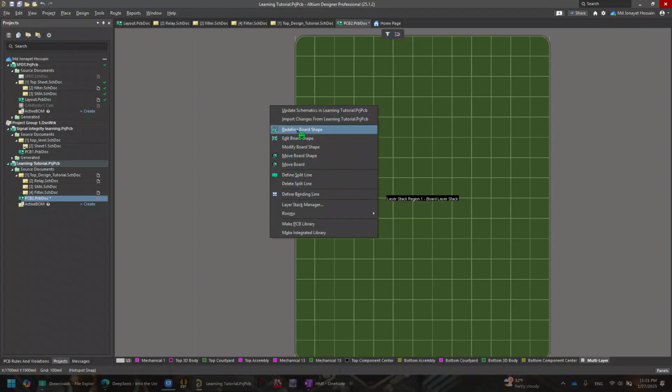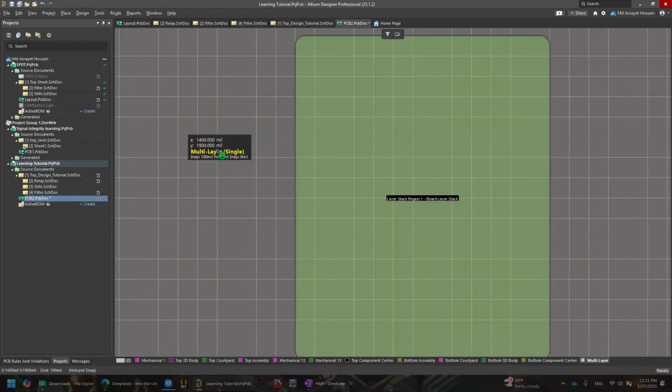This guy is very important because you can redefine your board shape entirely. And when you're gonna redefine your board shape, this little guy here becomes very handy. So on the redefine, if I want to make it a little smaller, you can do the same thing, and you can just always do shift and space to go into your curve mode or into a 45-degree angle or some other.